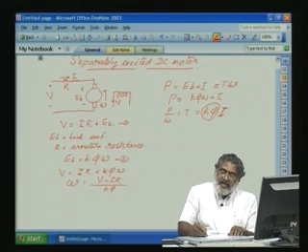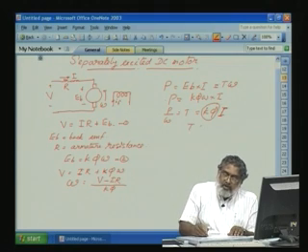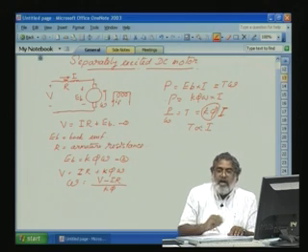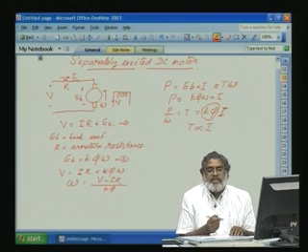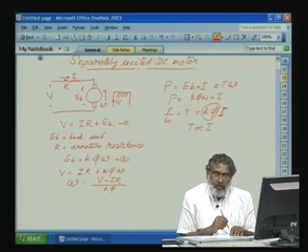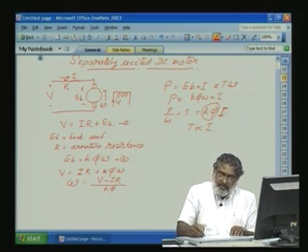So, if you see here, for a machine this k phi is a constant, that means torque will be proportional to our input armature current. So, to vary the torque we have to supply a variable Ia depending on the torque. To increase the torque we have to increase current, to decrease the torque decrease the current Ia. Okay. So, now this equation, this is the fourth equation.